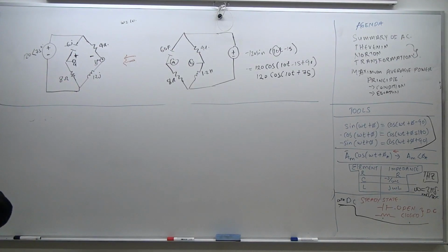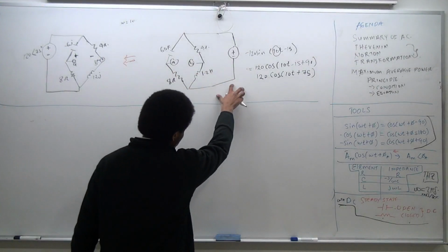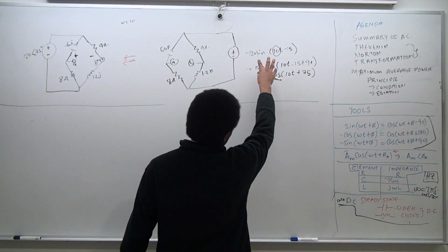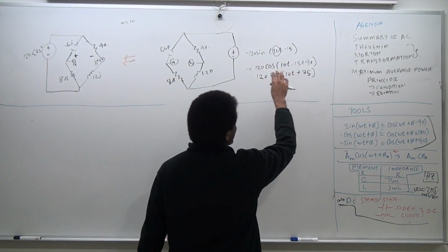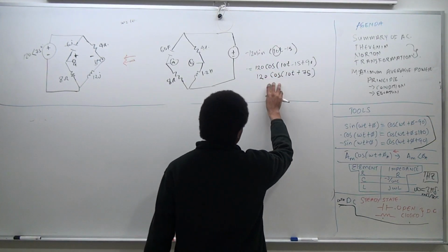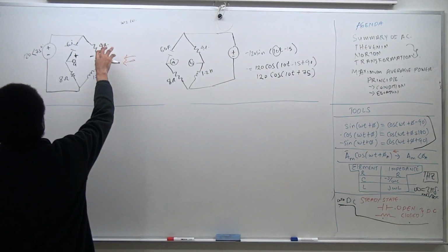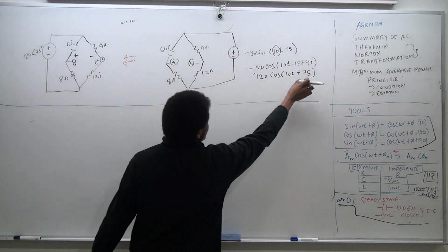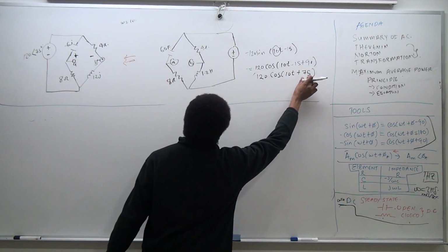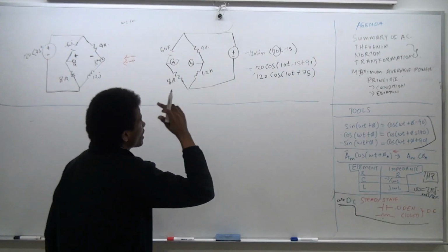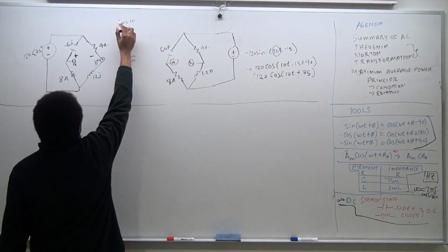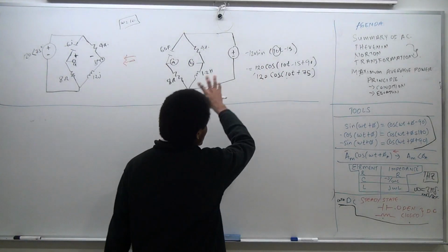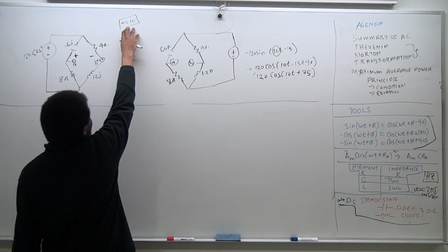The second thing, when you look at this problem, is, let's say the problem was given to you as this. I told you, if they gave you the problem with a negative sign, you would use these formulas to reduce the sinusoid to a common base where you're using cos as your basis function. That's the first step. Second step, you convert the cos into a phasor, as we did here. Very easy. You take the amplitude and it comes here. You take the phase, forget about the temporal information for now. The phase is 75, it comes here. Again, what's lurking in the back of our mind is that omega is 10. We have to put this down. You might think it's a simple step, but when you're dealing with multiple frequencies, this can get confusing. So you have to be conscious of the fact that omega is equal to 10.